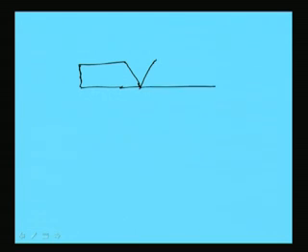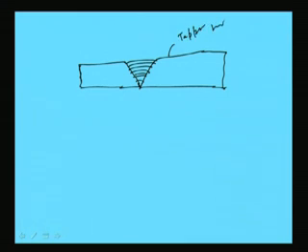Okay. Now, if we draw this butt weld, how does it look, let us see. Say one plate is something like this. Now, this can be joined like this. So, this is the welding face, and this tapering will be not exceeding 1 in 5. So, this tapering should not exceed 1 in 5 in this ratio. So, this is how the joint looks.